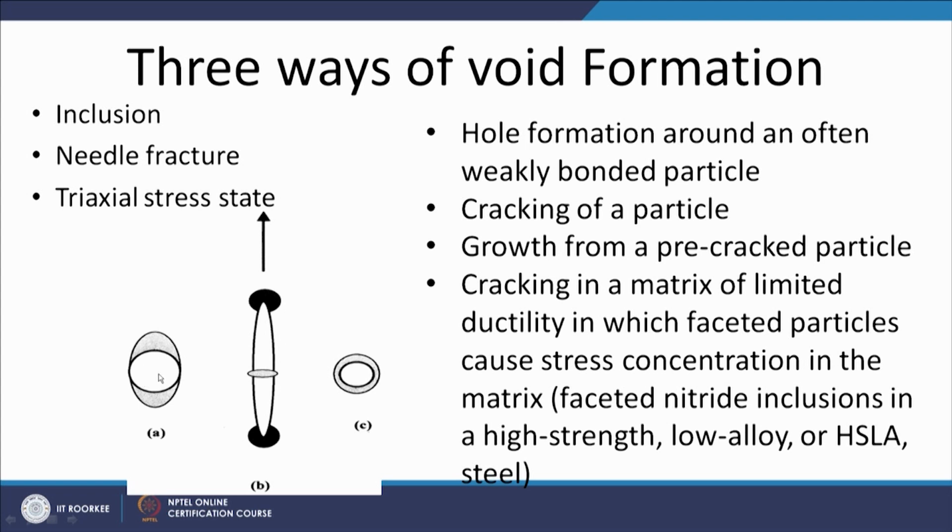This is the second phase particle, there is another second phase particle, and this is a third second phase particle. So, the second phase particle may be present in the form of inclusions, needles, or a triaxial stress state may exist. In all these three cases, how does void formation take place?